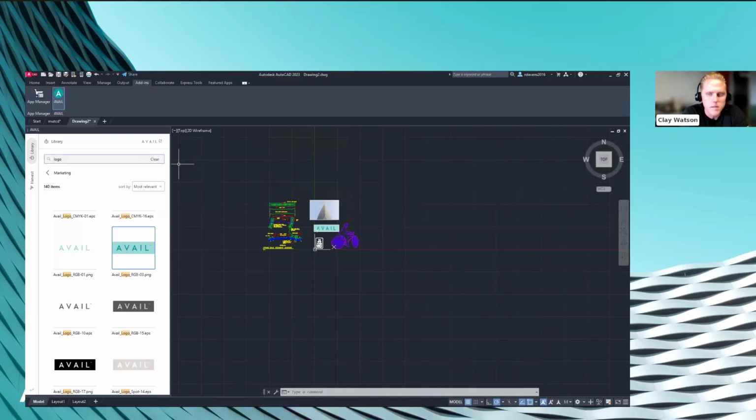And maintaining it as a block. So if it was a block, that block is getting written out into a separate DWG file and comes back in as a block. And that's why then the choice of, would you want this to maybe explode on its way in? Because we can do that with our plugin. If it was tagged, I'll just use that word in AVAIL as explode on insertion, we could basically program our plugin to, when that asset's being brought through with AVAIL installed, automatically explode that after you've placed it, or scale it or rotate it. Any of those kind of parameters that you're used to.